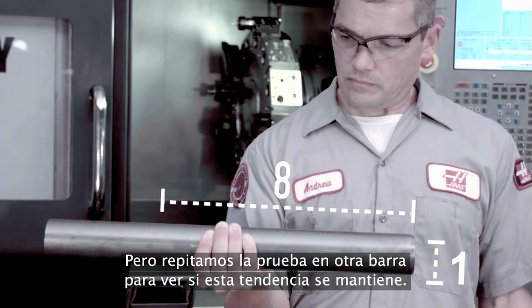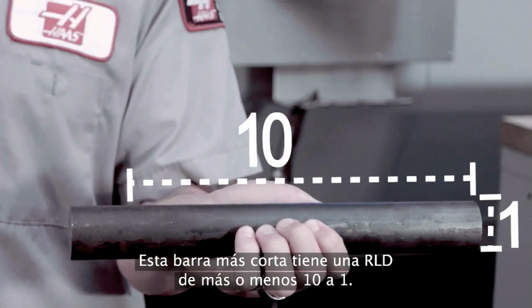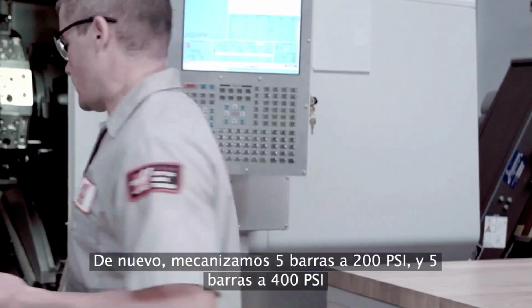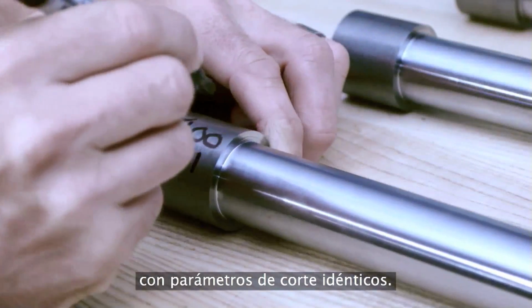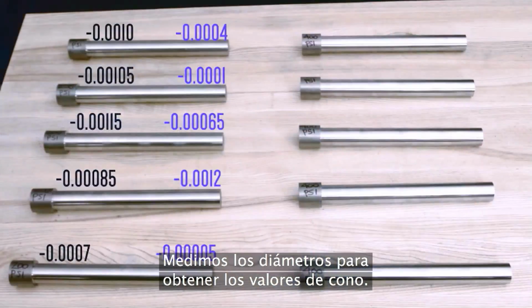But let's repeat this test on a different shaft to see if this trend holds up. This shorter shaft has a supported L to D of about 10:1. Again, we cut 5 pieces at 200 psi and 5 other pieces at 400 psi using identical cutting parameters. We check diameters and find our taper values.